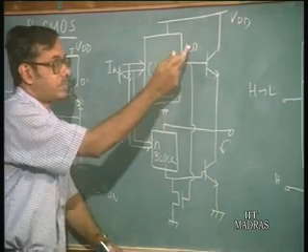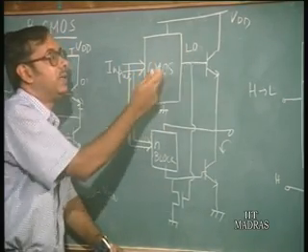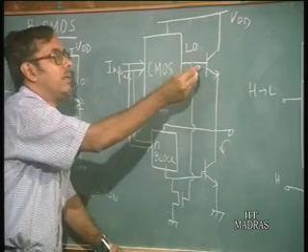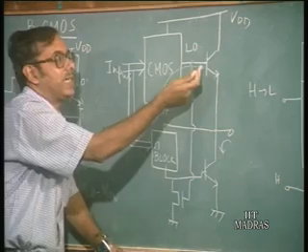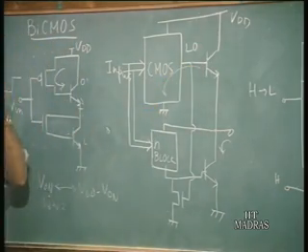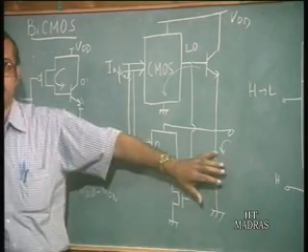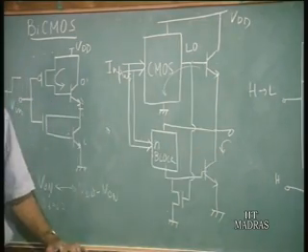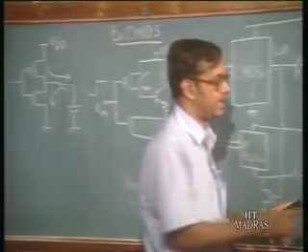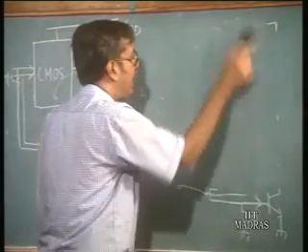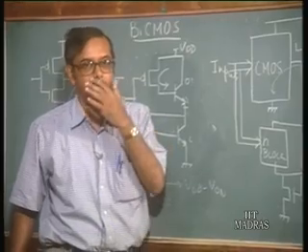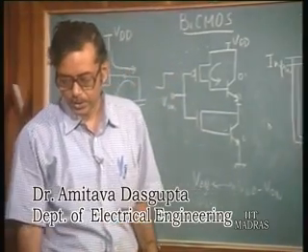Also, since this is a CMOS, you have an N block here which turns on, and that N block here in the CMOS is going to discharge whatever base charge is there in this upper bipolar transistor. So, in this case the output is going to go low, because the lower bipolar transistor turns on, the upper bipolar transistor is off. So, this is the basic circuit of the BiCMOS, any BiCMOS gate. So, any CMOS gate can be converted to a BiCMOS using this particular circuit.